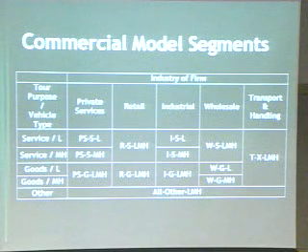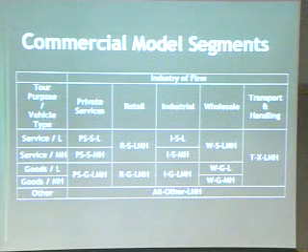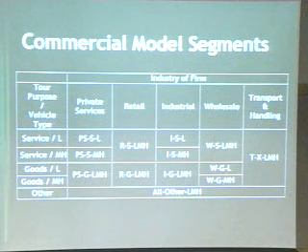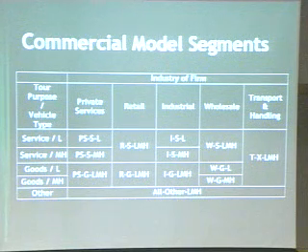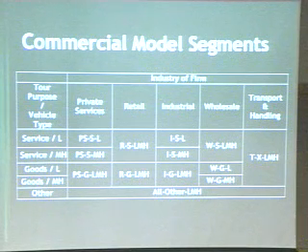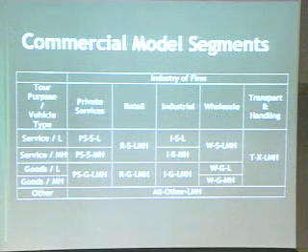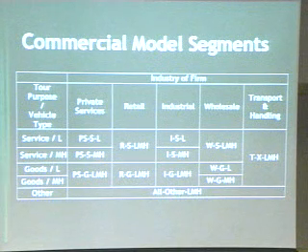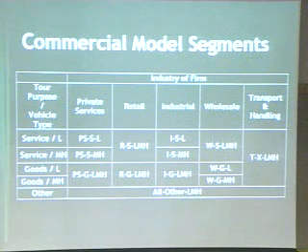We wanted to have a series of different models assigning the probabilities for the Monte Carlo process, trying to group together different types of tours being made, hopefully getting ones that had similar sensitivities so that the attributes were representing a group or a market segment, if you will. So we have the tour purpose and the vehicle type as the two things distinguishing. Services, goods, or other as the tour type. The vehicle type is light, medium, or heavy. And the type of industry that the firm is in, with those 5 basic categories that I described earlier.